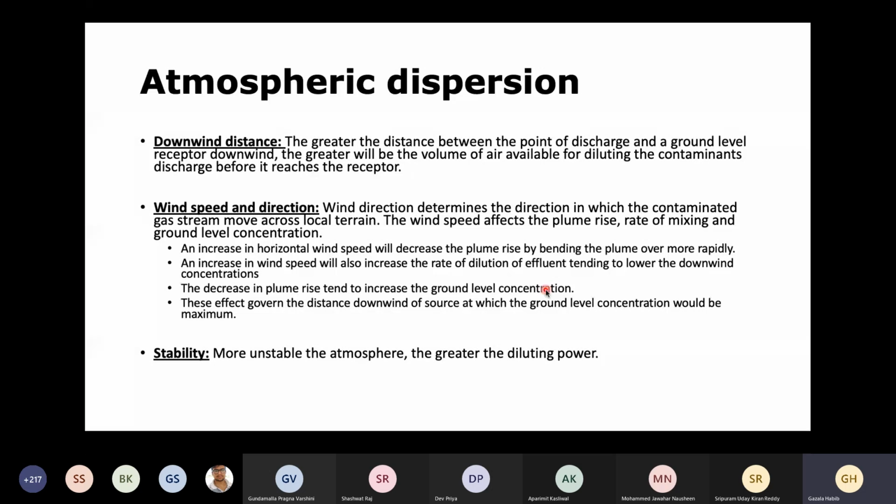That is one of the most important criteria in deciding the expansion of the city, and development of an industrial zone inside or outside the city, and so on. So downwind distance is very important. The distance of the source from the receptor side, where the residential and commercial establishment is, governs the whole dispersion calculation.